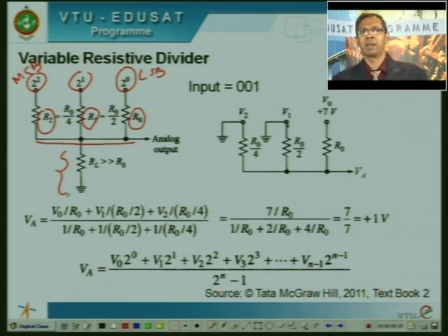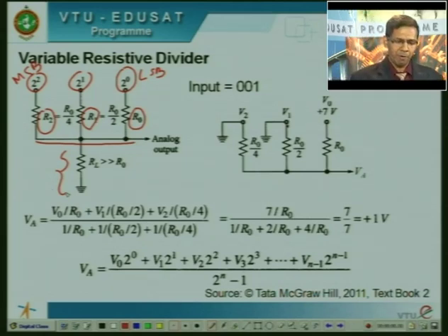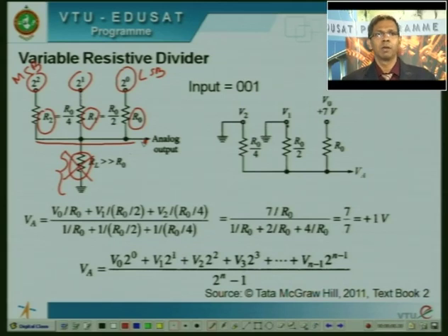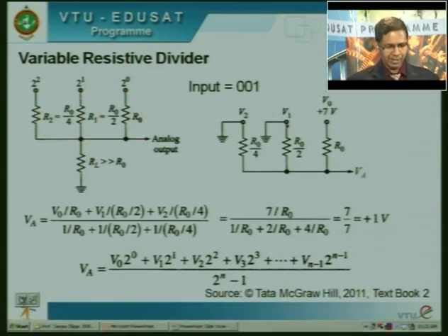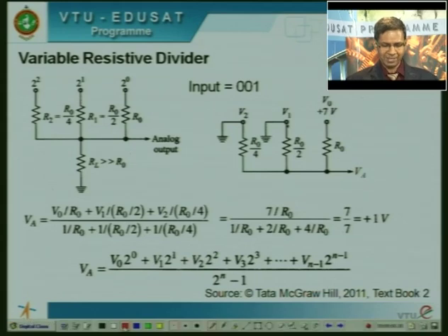We know that op amps have very high input impedance, to the extent that we can almost ignore it as an open circuit. So, for all further investigations, we are going to simply ignore this and treat it as an open circuit and simply say that the analog voltage is at the node of all these resistances. So, how is it that we are going to measure this particular value? For that, let us again take the aid of an example.